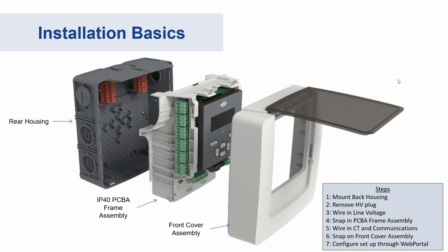If you want to see more than 62 days of data, then you're going to either export reports from the meter itself at least every 62 days, or pull that data into an energy management platform, where you can look at the data and run that software's trend data. So the short answer is both. There's 62 days built into the meter itself for trending, or longer term via an energy management platform.